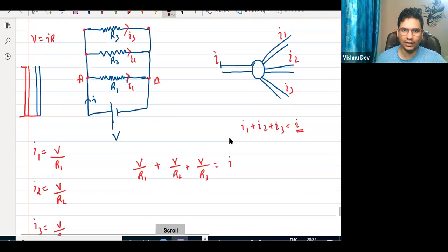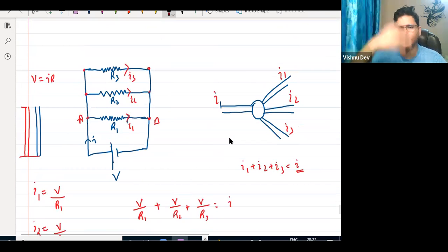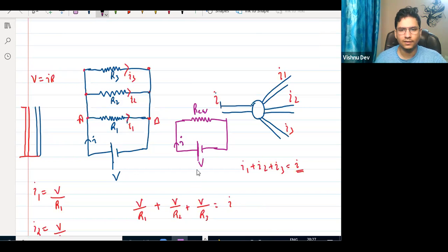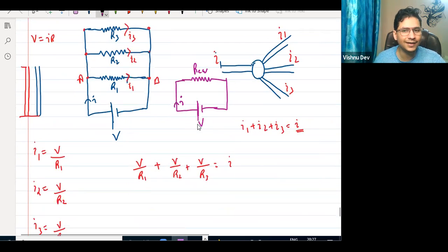जैसे मैंने ऊपर series में किया था, मैंने सारे रेजिस्टेंस को हटाकर एक रेजिस्टेंस लगा दिया. So instead of that, can I say that इन तीनों को हटाकर अब मैं बस एक रेजिस्टेंस लगा दूं, एक रेजिस्टेंस सबको हटा के. Call this R equivalent, right? Same, एक resistance. Current तो same रहेगा ना? अब बताओ, in this case, I will be equal to what? I will be equal to V by R equivalent. Yes or no?